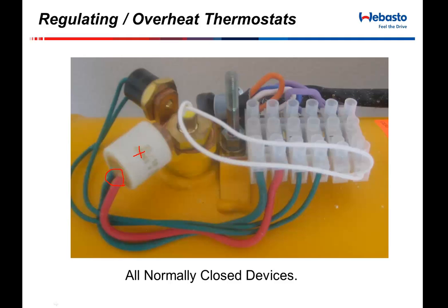So we can control really whatever temperature we want this heater to run at simply by changing that part. If we wanted to run it cooler or hotter, we can put different thermostats onto that product or onto that port.